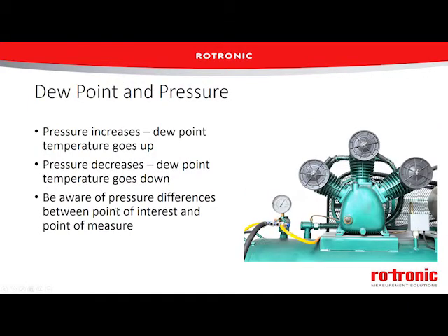If you're in, for example, a compressor system, or a compressed air system rather, as pressure increases, the dew point temperature will also increase. And if you continue to increase pressure in some air, eventually you would reach saturation and you would get condensation just from that pressure increase. As pressure decreases, your dew point temperature will go down. You're going to get a bit drier. And be aware of pressure differences between the point of interest and the point of measure.